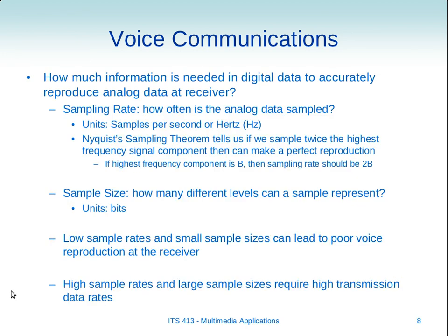What do we miss? I think we've summarised that. What is a good sampling rate? Nyquist has a theorem that says twice the highest frequency component. If the largest frequency component in our signal is 4 kilohertz, the sampling rate should be 8 kilohertz, 8,000 samples per second.